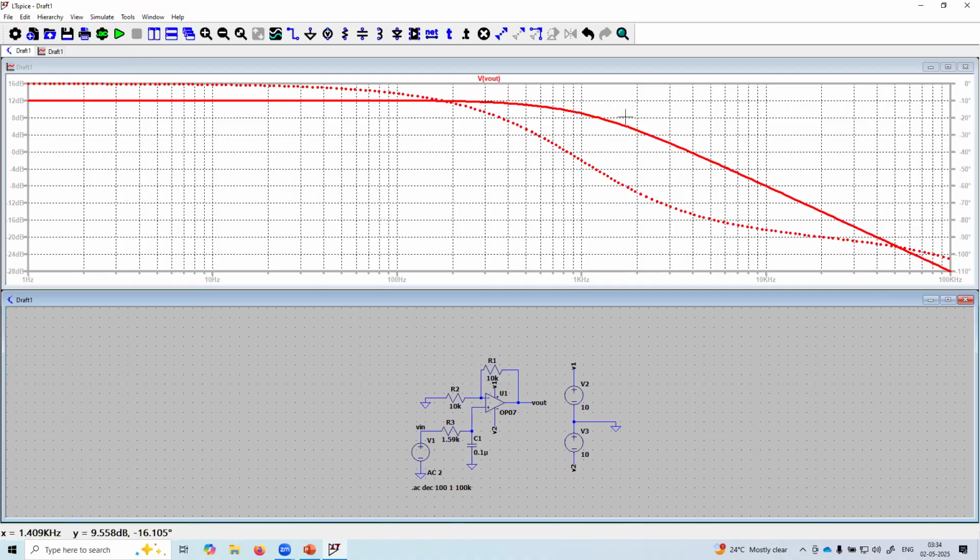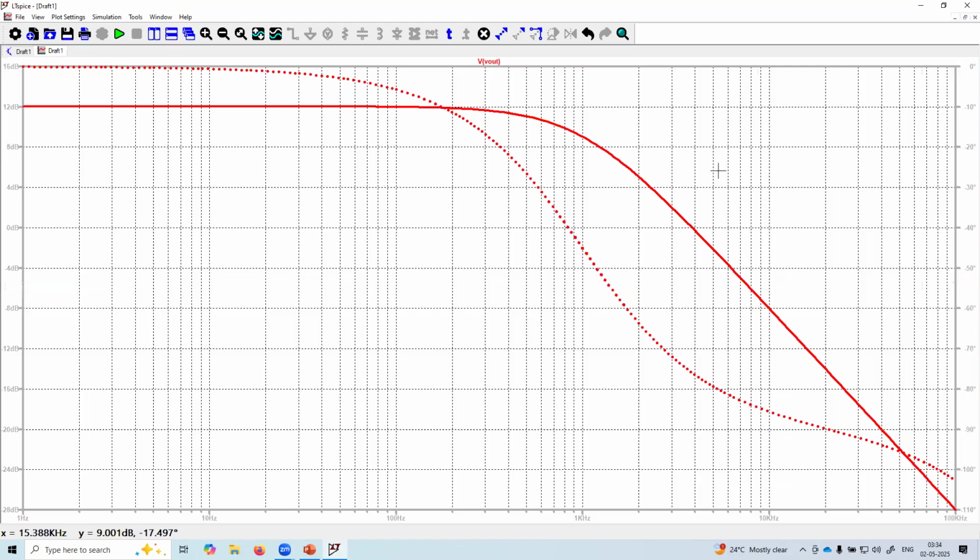Now you can see this looks like the low pass filter response that we have already discussed in the class. From here you can find the 3 dB frequency. You can check whether it's coming or not. You can go till the 3 dB point, you can see it in this place. So this one is approximately 998 hertz. That means it is close to 1 kilohertz.